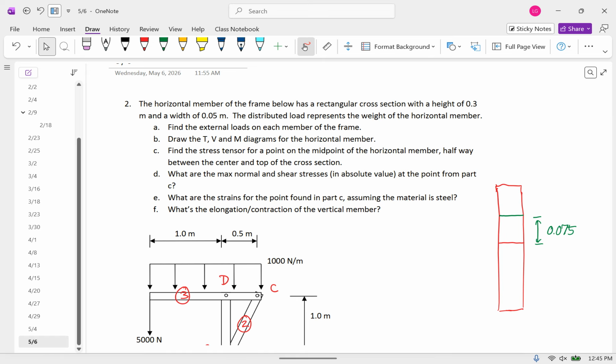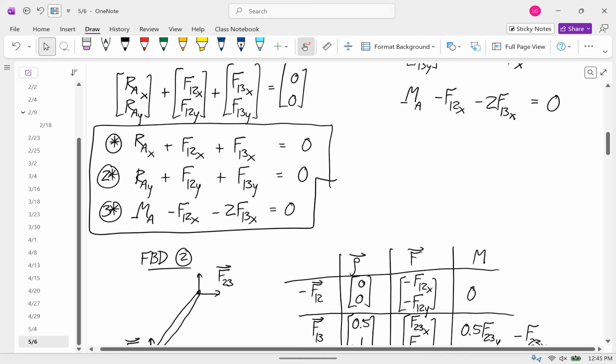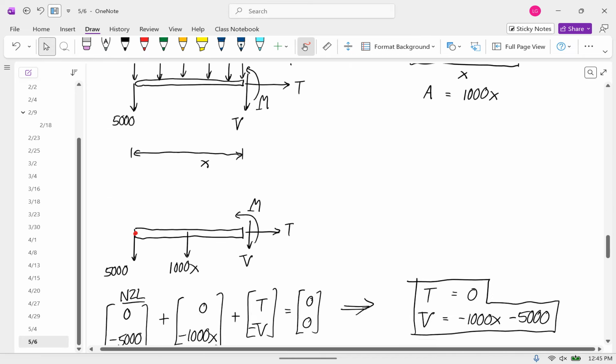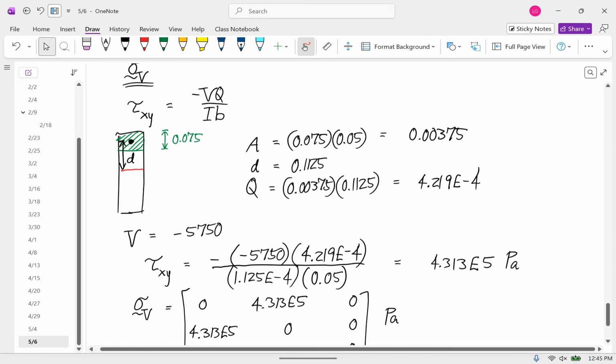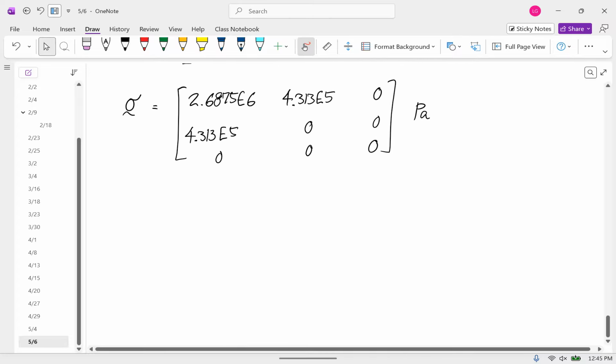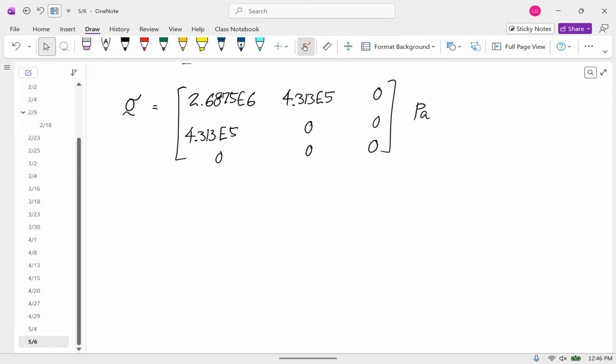Okay. So now what are the max normal and max shear stresses? Well, what are we going to do to get those? In order to get the principal stress, we need to do eigen. Yep, that's right. So we'll just calculate the eigenvalues of this. That'll give us our principal stresses, including our maximum normal. And then we can just use the formula for the maximum shear.